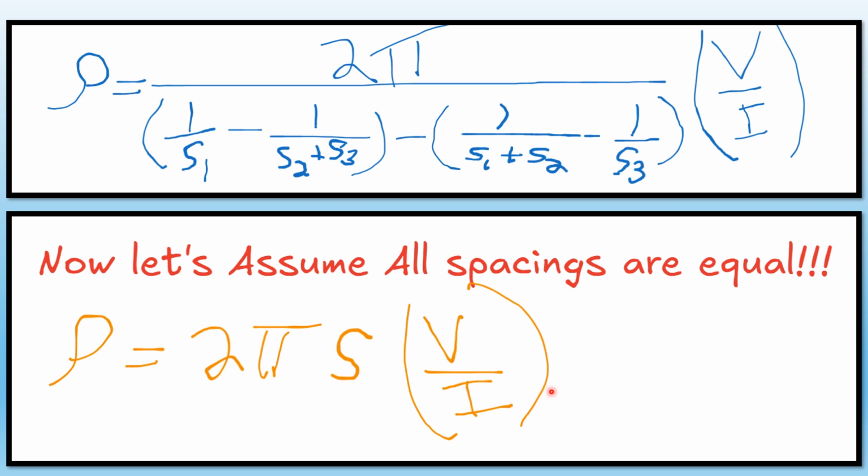And we're doing voltage over current measurements when we're doing resistivity. So that means our calculations just got a whole lot easier if we're just given voltage and current from what we're looking at, and looking at probably our manuals or our data sheets for the device or the instrument that we're using. We could find out the spacing. You could even measure it yourself, and you could get the resistivity.